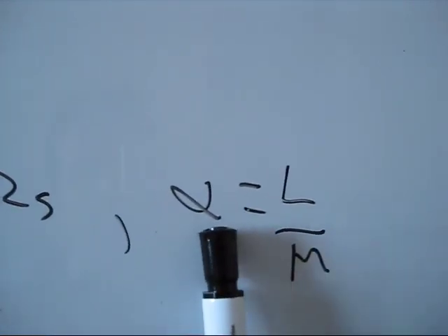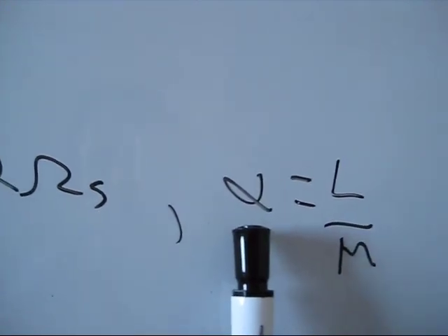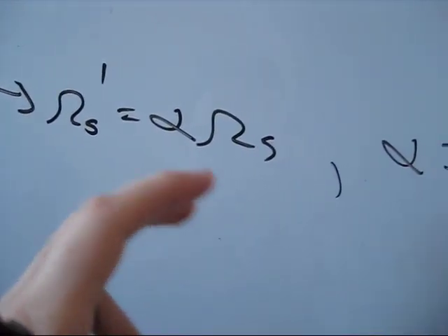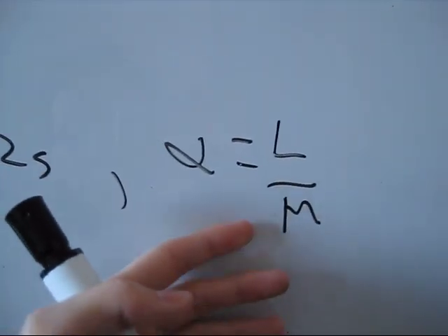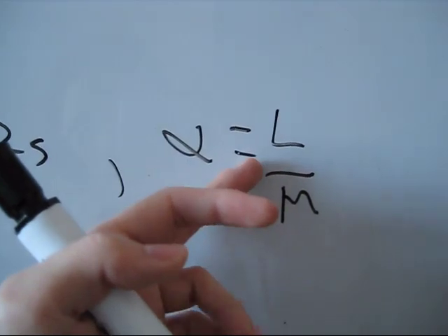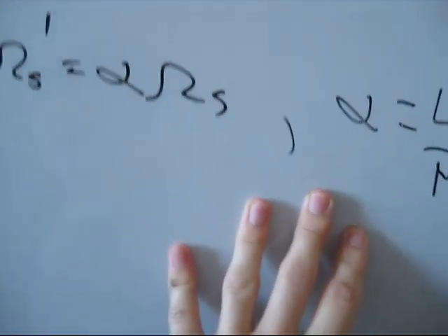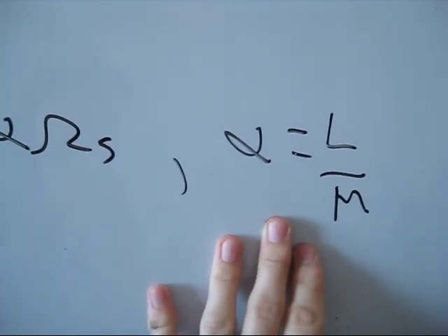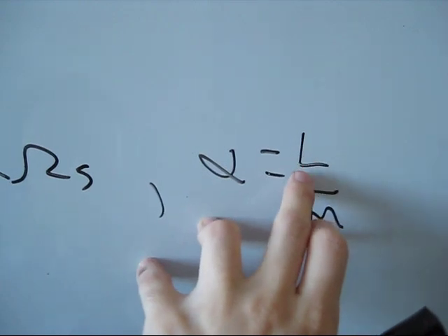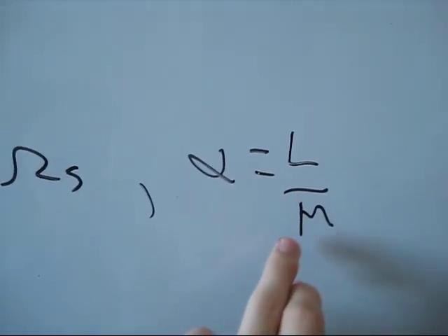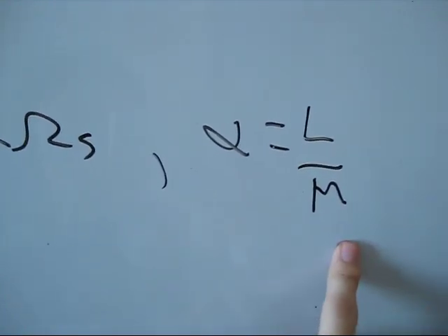So as long as you can express the factor with which you wish to adjust your original sampling frequency as a fraction, you can then use a combination of interpolation and decimation to produce your desired result. So how do you combine these all together? Well, for interpolation we had to interpolate, then low pass filter, and for decimation we had to low pass filter and then do the actual downsampling part.